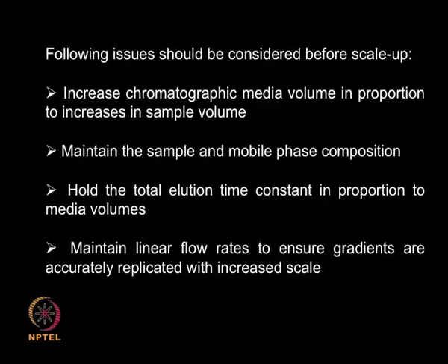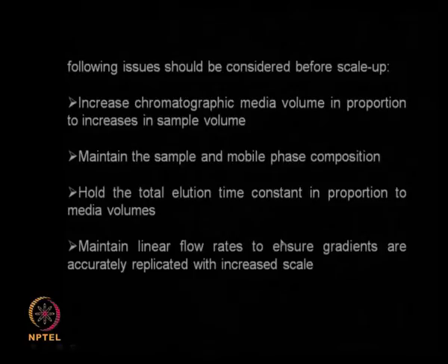If I am doing a protein purification in the lab and my elution time is 35 minutes, I do not want to be running for hours. If I am going to scale up, I want to see whether I can achieve the same elution time, that means the same 35 minutes. So if I am going to increase the media volume, how much will the elution time change? So I need to consider that aspect also.